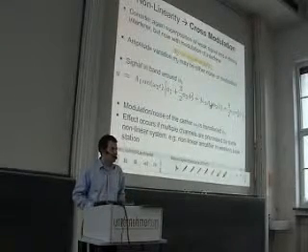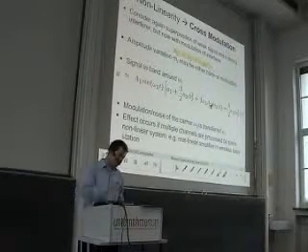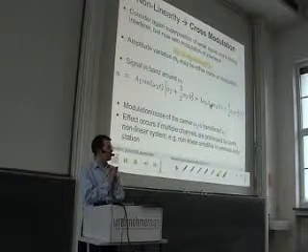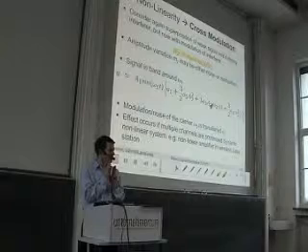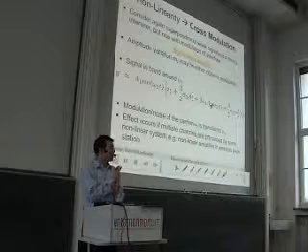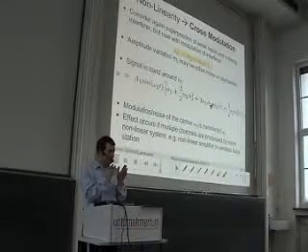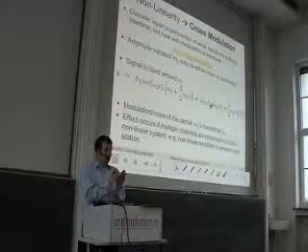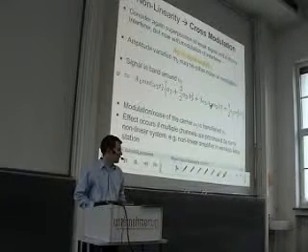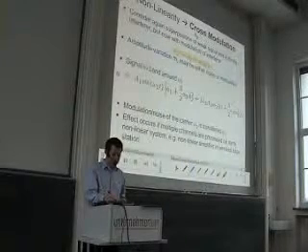This, for instance, can be an effect if we go through a common nonlinear system with two communication channels, because then the data on one channel is transferred to the other channel and becomes visible there too. Although these are different carrier frequencies and different channels, the nonlinearity makes a transfer of the information contained in these two data. And this is what people call cross modulation.